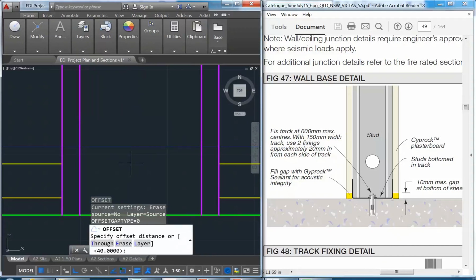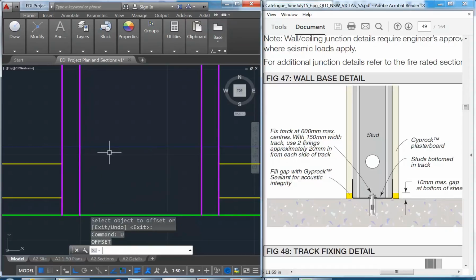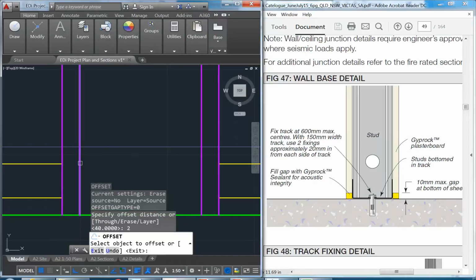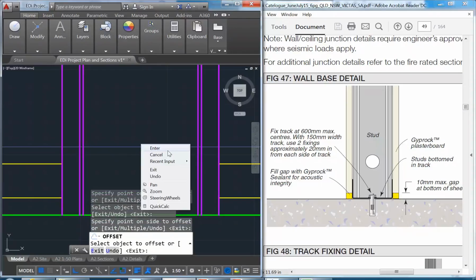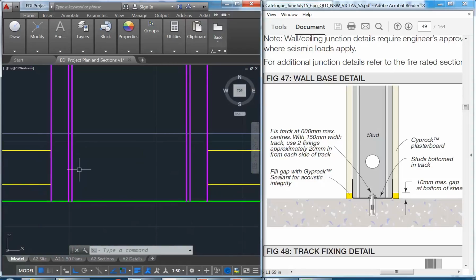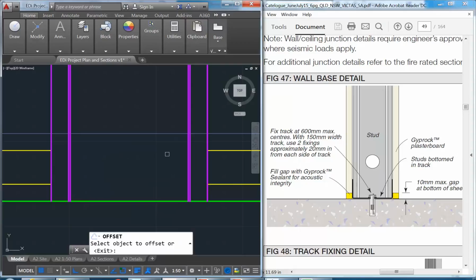And then I'll just offset 5 mil, or even see if we can go down to 4 mil. No, that's plenty actually, so I can go right down to maybe 2 mil. You would never do this the real size. In reality, it would be less than a millimetre thick. But if you draw it that thick, you won't see it. So actually 2 mil is even too much. So maybe I can go down to just 1 mil. Yep, that's alright.